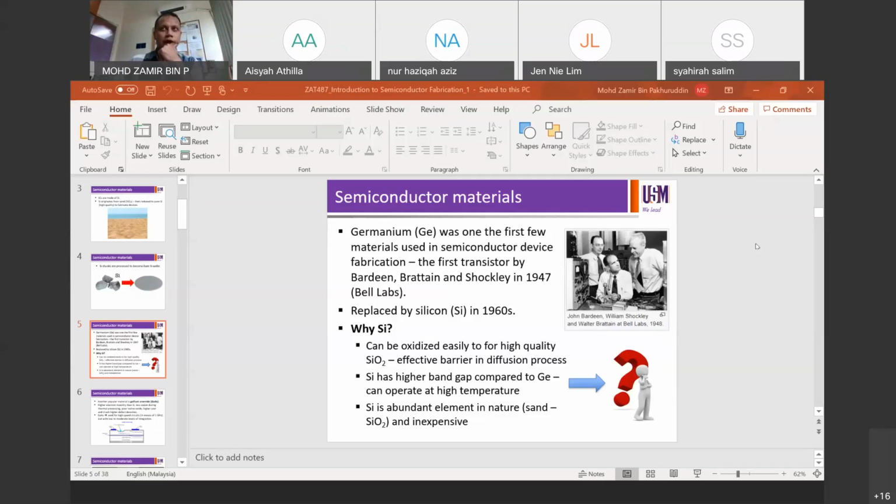The higher the temperature we go, the more valence band electrons get excited into the conduction band for the conduction process. So if you use a higher band gap material, you're going to end up with a more stable device. It's not going to be affected by thermal excitation at high temperature. On the other hand, if you use a material with lower band gap, it's easily affected by thermal excitation, even if you increase the temperature slightly. So a higher band gap device is therefore more thermally stable.